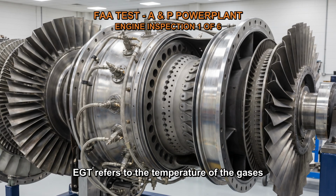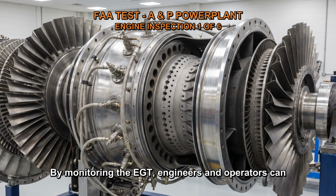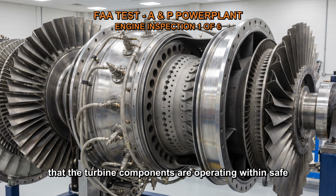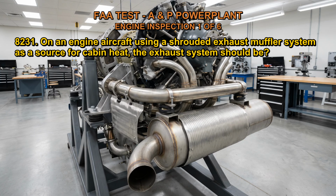EGT refers to the temperature of the gases exiting the engine's combustion chamber. By monitoring the EGT, engineers and operators can assess the engine's performance, combustion efficiency, and ensure that the turbine components are operating within safe temperature limits.